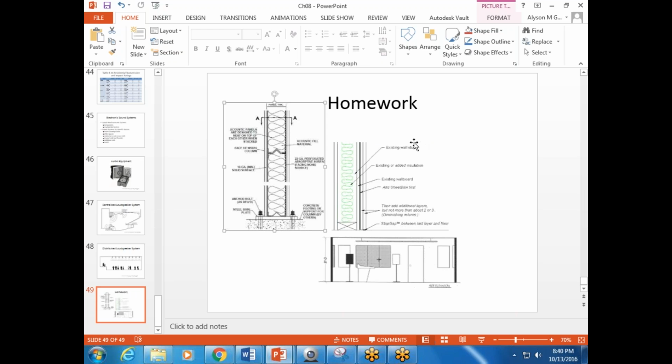But you might give me more information on the book, so the book says it's different sound if you have 1 inch or 1/2 inch gypsum board versus 5/8 inch gypsum board on the outside. So little details like that. I'm looking to see what would you add to the wall section in order to make it more acoustically sound.